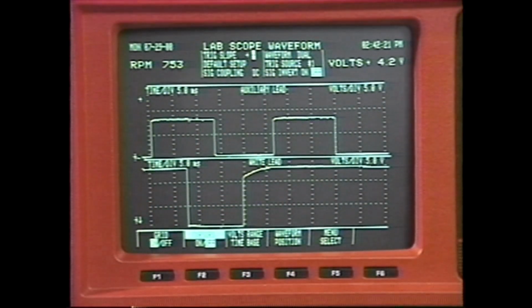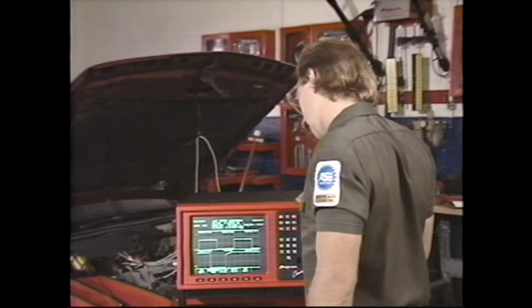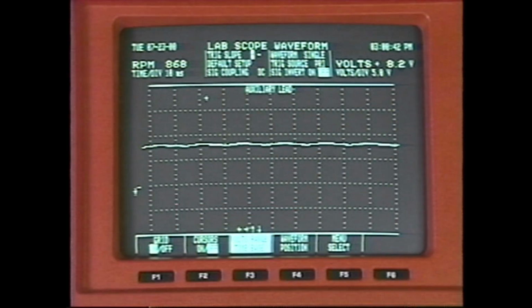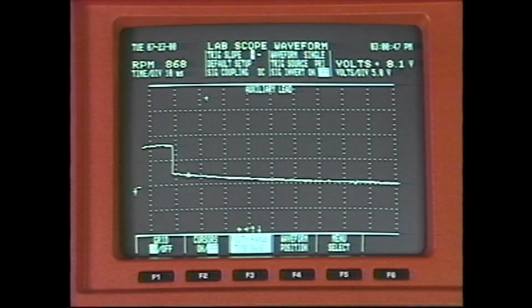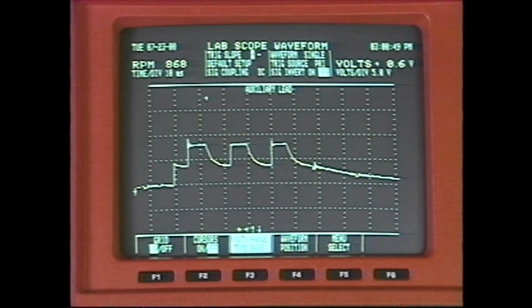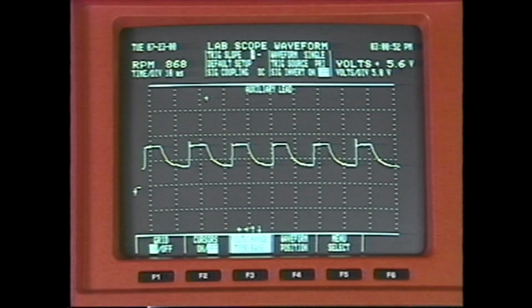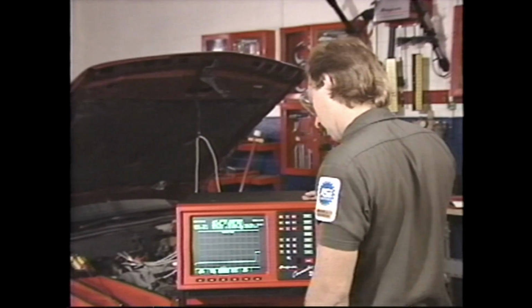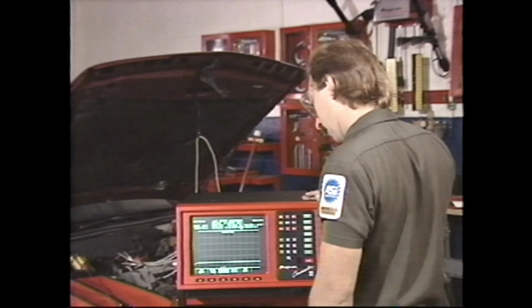The lab scope screen gives you a tremendous amount of flexibility and adjustability for displaying many different kinds of low voltage signals in detail. You can measure minute variations such as excessive AC ripple on a DC signal. You can also observe and measure voltage levels throughout the entire circuit, even on both sides of a resistor, to locate problem areas. How the lab scope is set up will affect how the waveform appears on the screen.